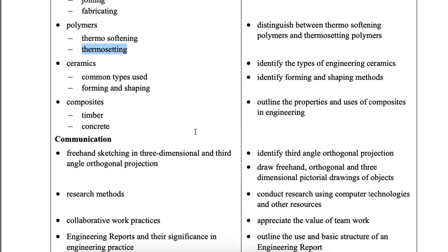The big two are phenol formaldehyde, which is a condensation polymer, and a copolymer. So it's made of two groups of phenol and one group of formaldehyde, and when they join together, they make the polymer, phenol formaldehyde, and water, H2O. So because of that byproduct, they call that a condensation polymer.